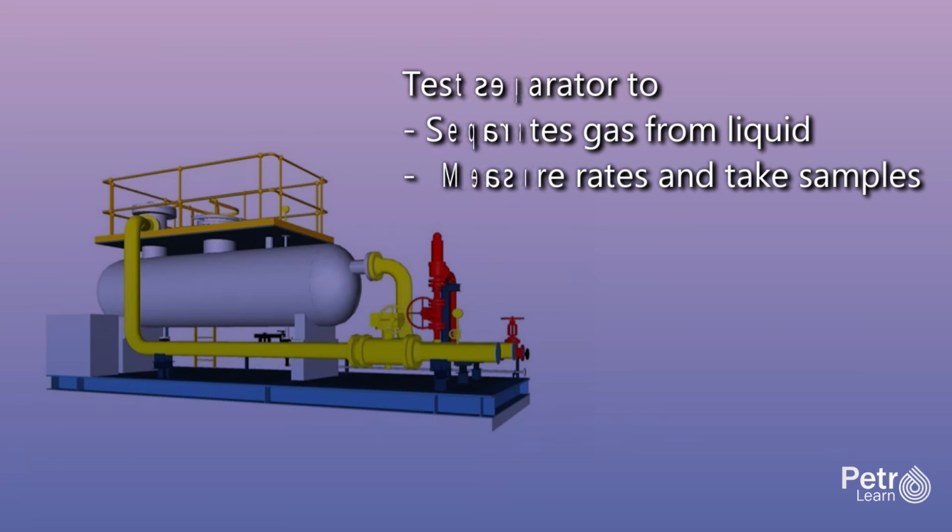Water production is also measured. The fluids are sampled for laboratory analysis. Oil samples are tested to determine API gravity, sulfur content, viscosity, and other properties that affect value and refining requirements. Gas samples are analyzed for composition, including percentages of methane, ethane, propane, butanes, carbon dioxide, hydrogen sulfide, and nitrogen. The presence of hydrogen sulfide, which is toxic and corrosive, requires special materials and safety procedures.